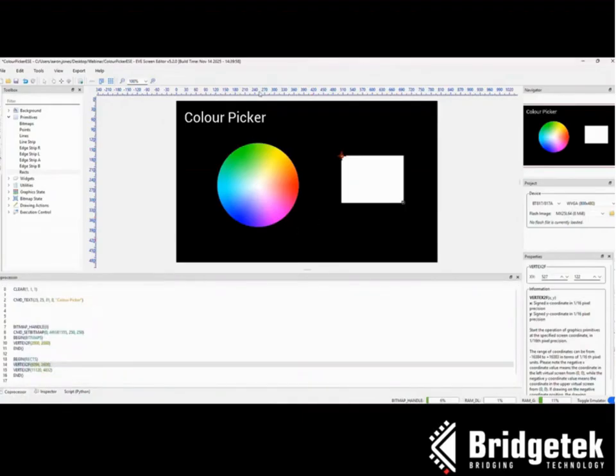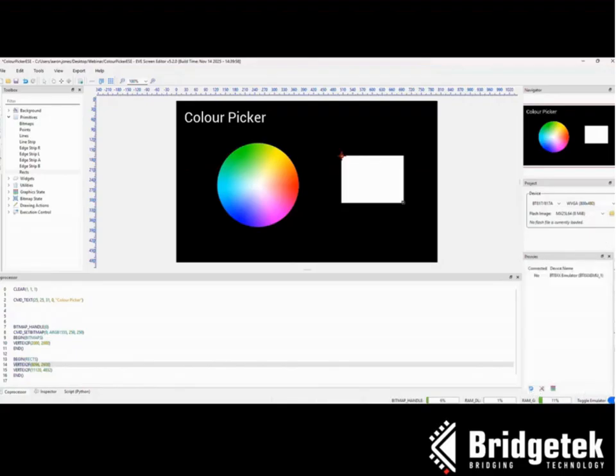We want to test them on hardware, so we can use our 4222 on the ME817EV again. So let's check that we have our project settings correct. We've got it set for a BT817, and we have the resolution set to WVGA. So there's a multitude of WVGA screens, and we might want to change the settings for these. And you can see that the devices currently only list the emulator, which you can run on ESE. But let's refresh, and you can see that the 4222 has appeared.